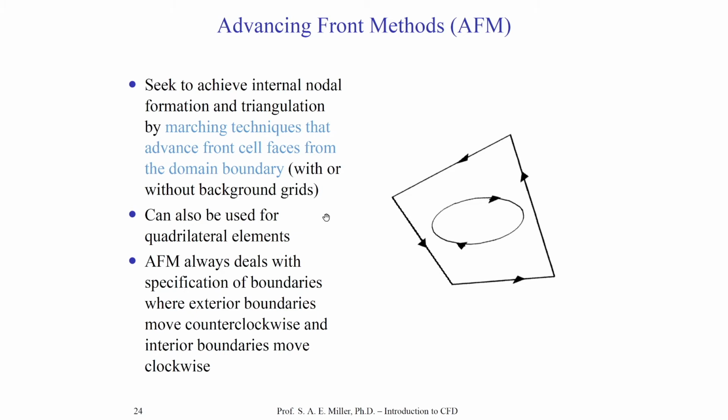It can be used for triangles, tetrahedrals, and quadrilaterals quite easily, and all these are implemented in most computational domain solvers. The advancing front method is called that just because of what it is. It is going around the boundaries, especially where you want to resolve the grid highly, to iteratively place grid points within the domain.